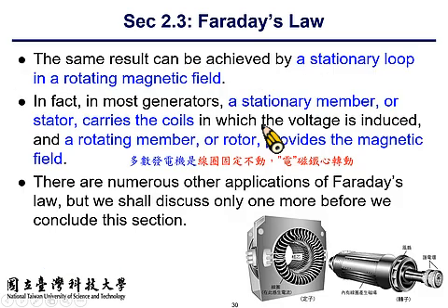So here is a more practical illustration of a rotating type generator. And to one's surprise, in this case, or in most cases, the loop is placed on the outside, while the magnetic field is produced by the rotor, which is also an electromagnet.